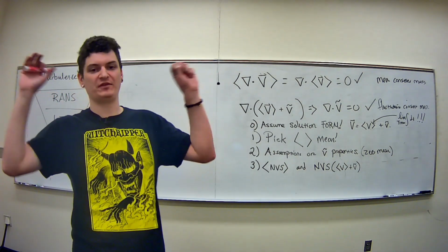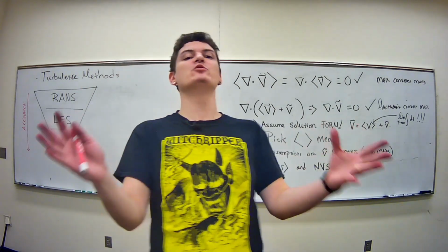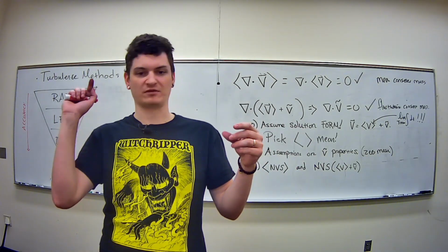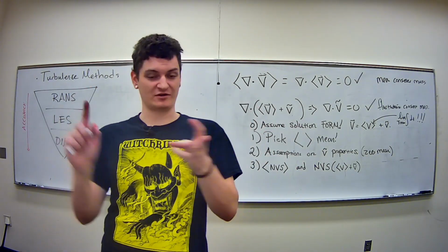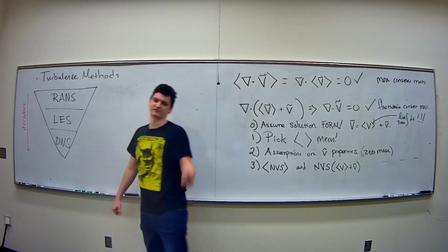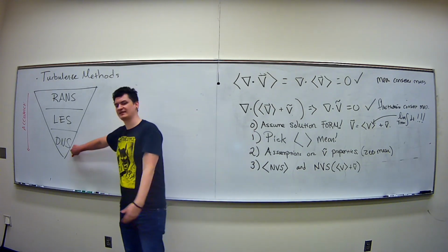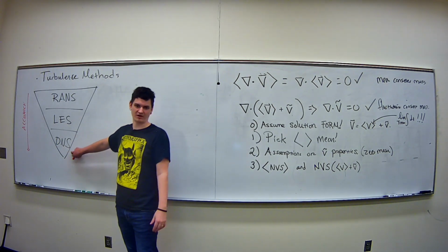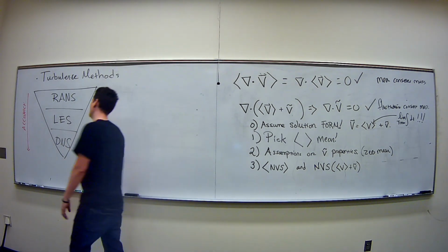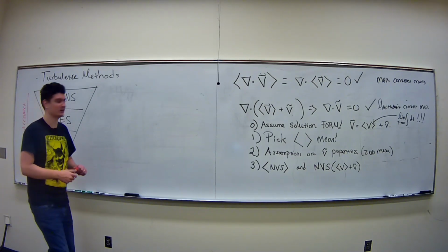DNS means solve the full 3D Navier-Stokes equations in a discretized fashion using a finite element or some numerical method. Make 0 assumptions about the solution form. Just make your grids tiny enough that everything works out. Focus on numerical investigations or be able to quantify your numerical error. Take those governing equations from lecture 1 and lecture 2, quit the class, learn numerical analysis, and solve it that way. Have lots and lots of money because you can afford server space that can run computers at that speed. Pay Star-CCM+ to do these simulations for you, and you can get really fine accuracy that you kind of believe, because the numerical error didn't blow up.